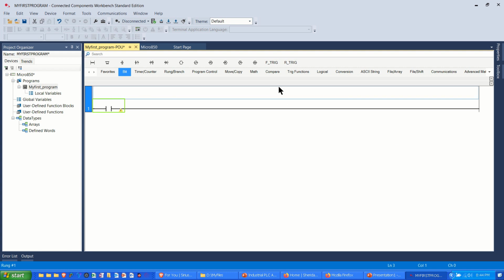The second section, I call the B section. That's where I build it out. I put the block instructions. I do all the business of the rung itself. And the last part is way off to the right, and it's the conclusion. What did A and B together give us? Our conclusion, C. So I'm going to put this here, and you can see it populated right over on the right hand rail. Outputs should always be on the right hand rail.